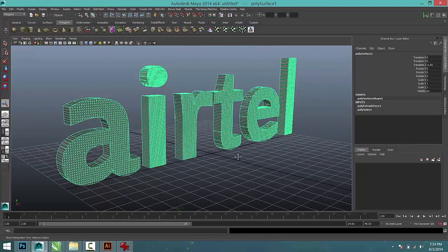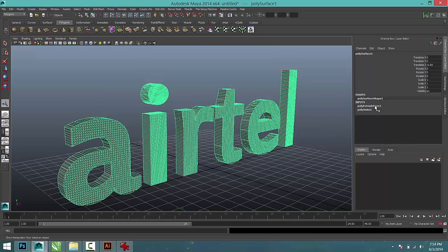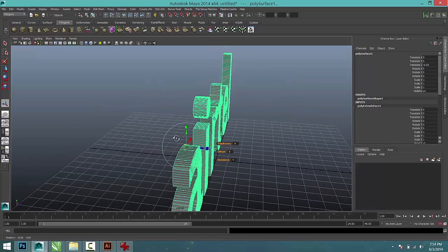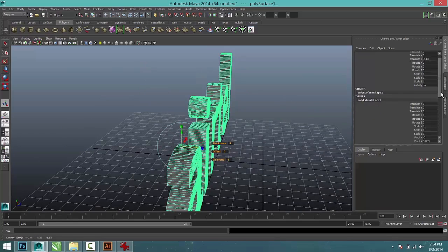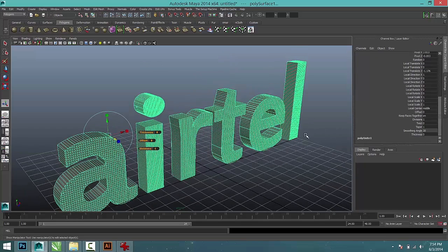All right. So here we are back with the created object. Note again that a new node has been added, which is the poly extrude face node. Now, if I click that, you can see that I almost returned to the action where I did the extrude. So I can actually still pull this again. That's the power that you have with nodes. You can return back, like I explained, and still be able to make some edits on what you have created before, so long as you haven't done too much above that to mess with the base object.